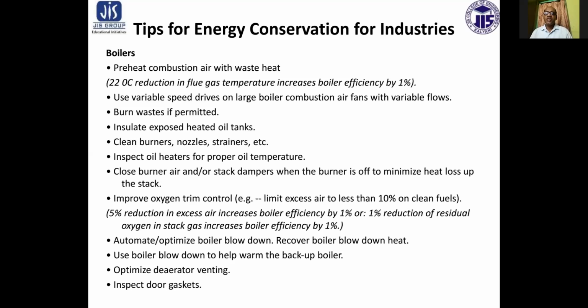Second, use variable speed drives on large boiler combustion air fans with variable flow. As we know, the power required fluctuates during the daytime and depends on season to season.